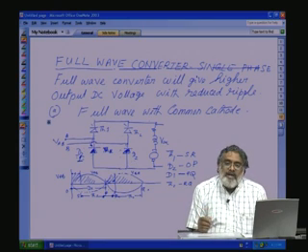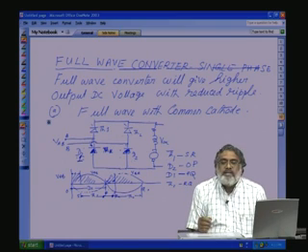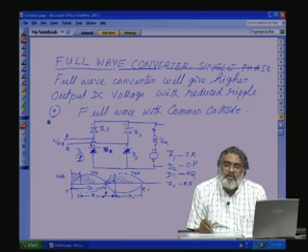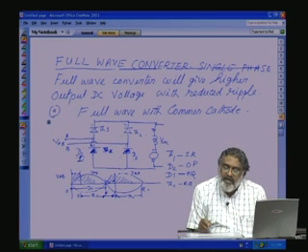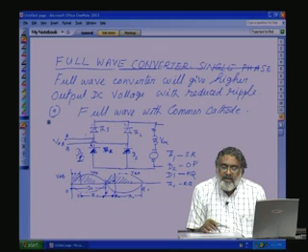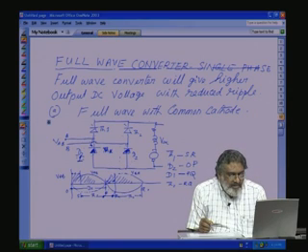Now take a case where the TH2 gate pulse fails, that means due to some mistake TH2 fails. What will happen? Current will keep on freewheeling through D1 and TH1, and since the load is highly inductive, current will not decay. The next time the voltage goes negative at the P point, the diode will conduct. So through TH1 and D2, as a half wave rectifier, it will keep on supplying power to the load.